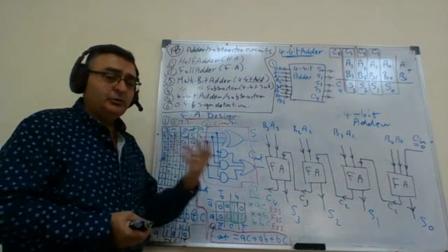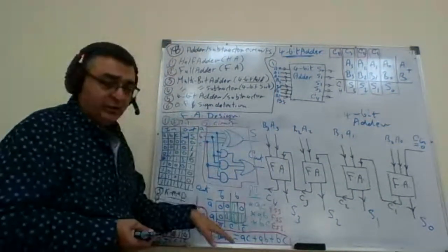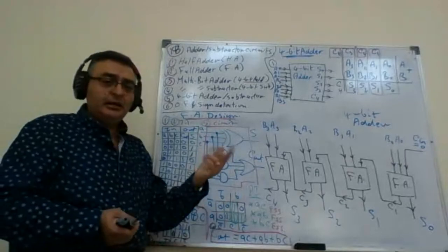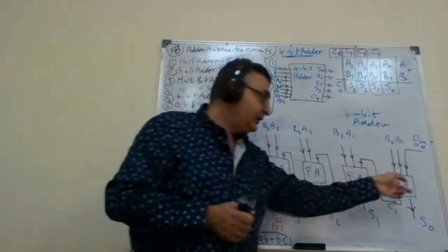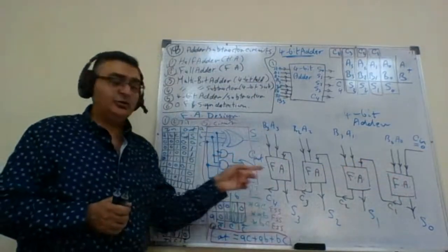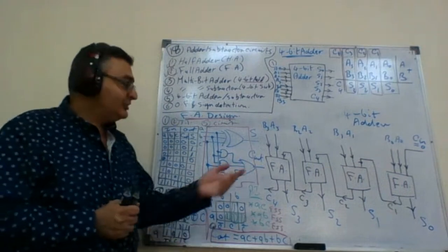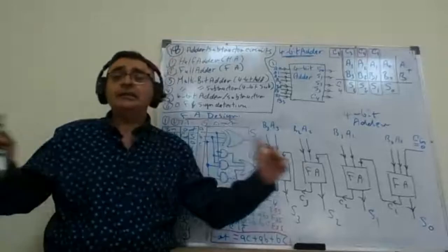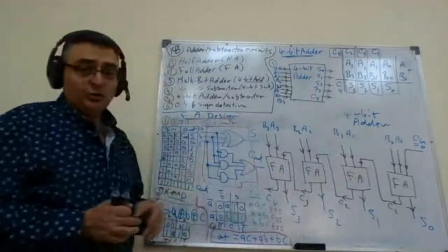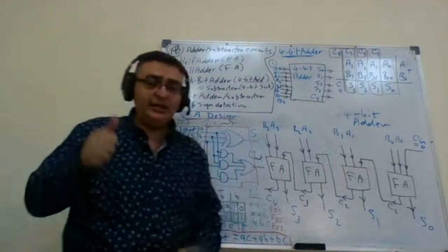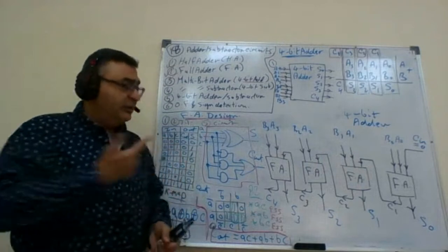Now I will go to the circuit engineer, ask him to design the full adder as we showed here just once. And I will ask him to replicate this block how many times? 4 times to get the circuit here. If I need an 8-bit adder, what shall I do? Just simply replicate more full adders here. If I need a 16-bit adder, we'll replicate the full adders again, and so on. So this mechanism can work. So one advantage of this design is the implementability and definitely the practicality, because we succeeded to do the design,